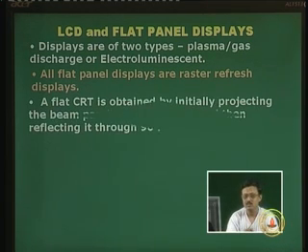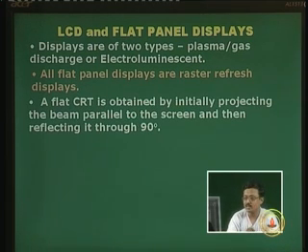Okay. So, we continue, and a flat CRT, unlike the monitor where you have a big arrangement of the electron gun, the anode heating element, and then of course the horizontal deflection plates, control grids, focusing unit, either an electromagnetic coil or deflection plates, horizontal and vertical, and then the beam passes through the shadow mask and has to fall on the phosphor coated screen dots.